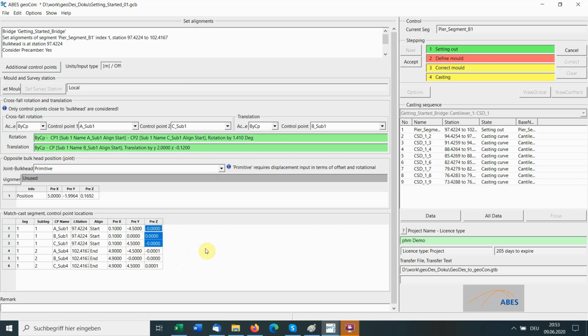That's the other thing we wanted to achieve with this operation. Again, we have a 1/10 of a millimeter crossfall variation towards the other side, the secondary bulkhead, and that only reflects our planned shift or change in crossfall.